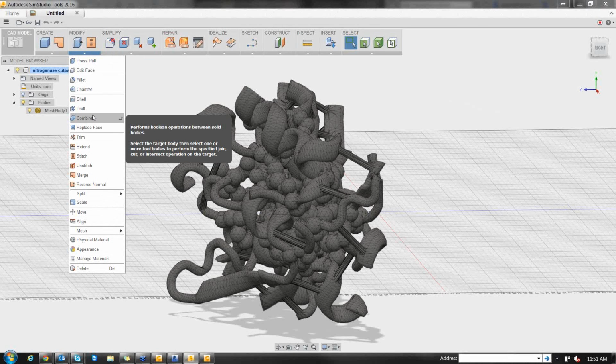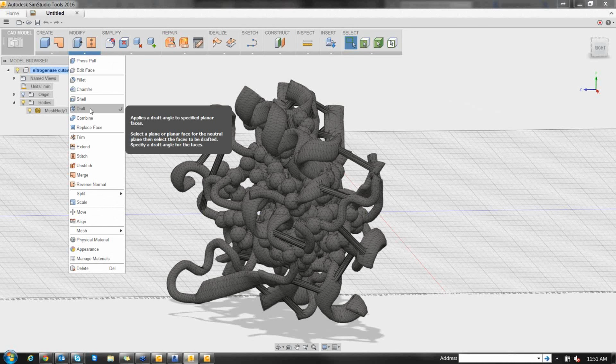Yeah, a lot of people, if the interference is macro enough, not some really small sliver, then they'll keep that and just suppress that in the surrounding parts. So Todd earlier on was talking about having an O-ring within the fitting, and a lot of people will keep those O-rings because they might just be designing flow through a valve and like, well, I'm going to suppress all the housing and the O-ring.